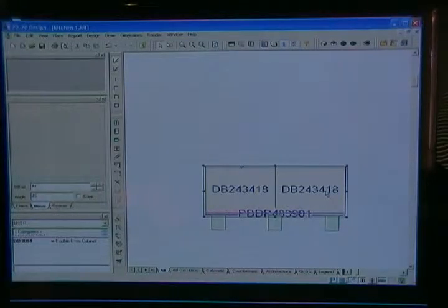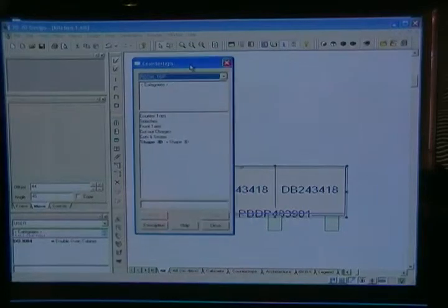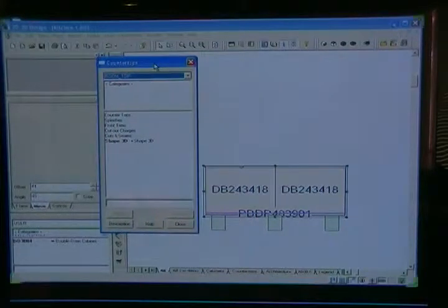All I'm left to do now is change that rectangle, which is 2D line work that will only show on a floor plan and not on a rendering. Right click on it, I'll get the rectangle option, and then go to make 3D. Now, make 3D will always change depending on what you're placing onto the floor plan.